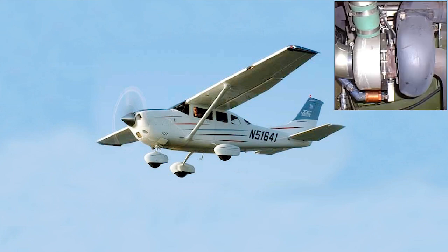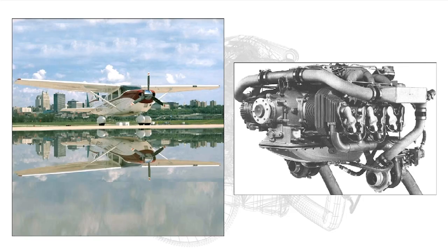In order to either increase engine power for takeoff and initial climb, and/or to maintain engine power at high altitude, the inlet manifold pressure must be raised artificially, and this is done by supercharging. Where a supercharger is used to increase the engine power output at sea level, rather than to maintain normal engine power output up to a high altitude, the engine will need to be strengthened in order to resist the high combustion pressure. This type of engine, like the one shown here, is fitted with what is called a ground-boosted supercharger.